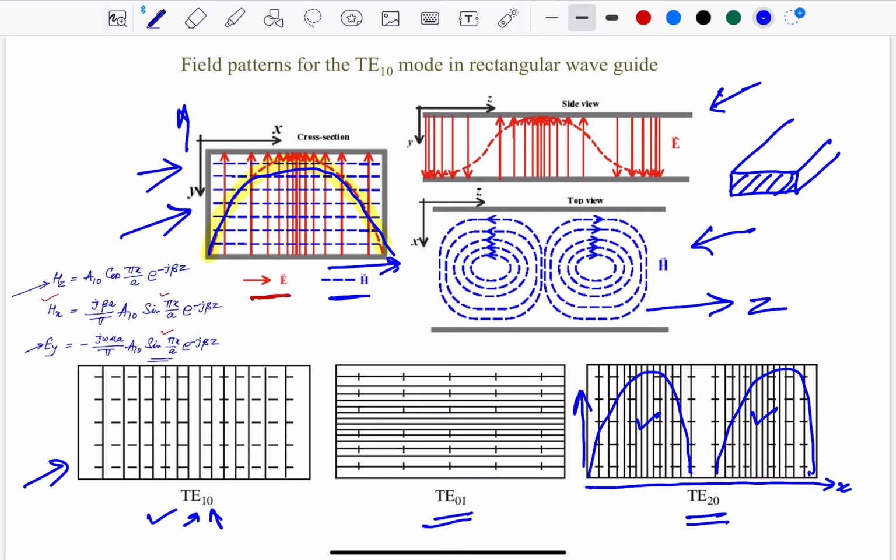So hopefully, by changing the variation, we particularly focus on modes like TE n0, so 3 0, 4 0 and 5 0, like that. The reason why we are exploring this is because of the coupling: in microwaves it is quite challenging when we are going to excite some higher order modes. So this is the field pattern of the TE10 mode. Hopefully this is clear to all.